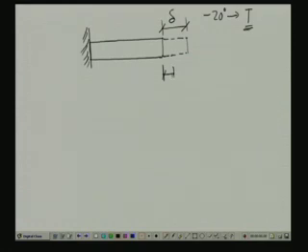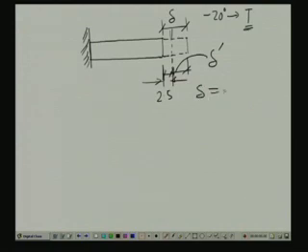has two parts. One is this initial 2.5 millimeter, which was unrestricted movement, and then subsequently it will be encountering the wall, and now since I have removed the wall, this is also moving freely, and let us call this particular distance as delta dashed. So, delta, the total deformation, is equals to delta dashed plus 2.5 millimeter.